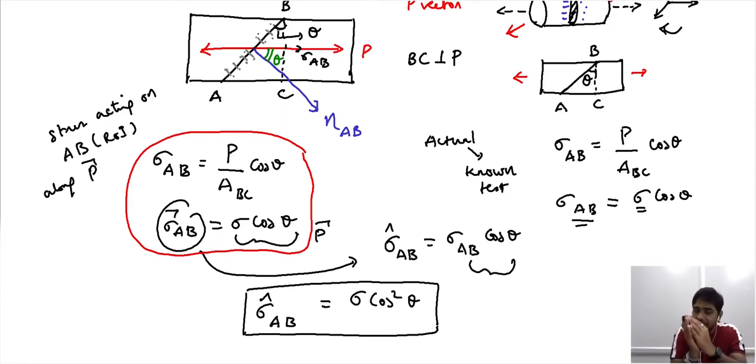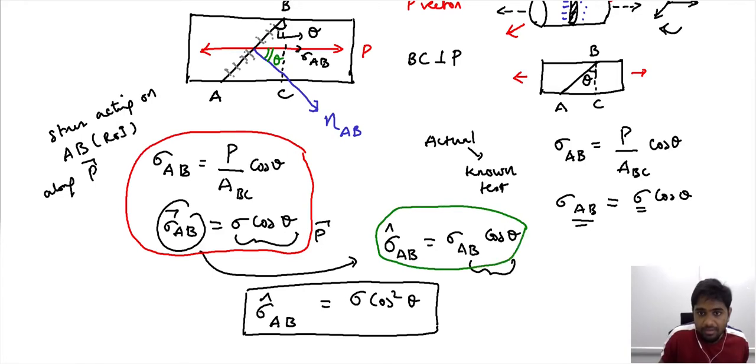But since AB is inclined, it is not very meaningful to us, because we need to understand the resistance offered along AB by the atoms. Along AB, the atoms are inclined in this way. Therefore, we are considering a normal to AB. The stress acting along the normal to AB can be expressed in this manner, and when you substitute and express it in terms of the stress already known to us, the stress that emerges from the experimental stress test conditions, we end up with this expression.